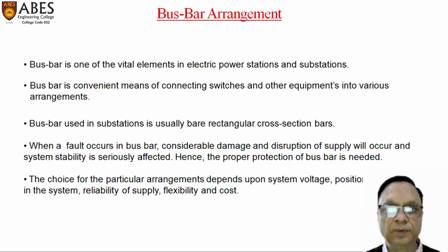Now first we should understand what we mean by bus bar. It is one of the vital elements in electrical power stations and substations. We'll always find it there. A bus bar is a convenient means of connecting switches and other equipment into various arrangements. Bus bars used in substations are usually bare rectangular cross-section bars, most probably made of aluminum metal.